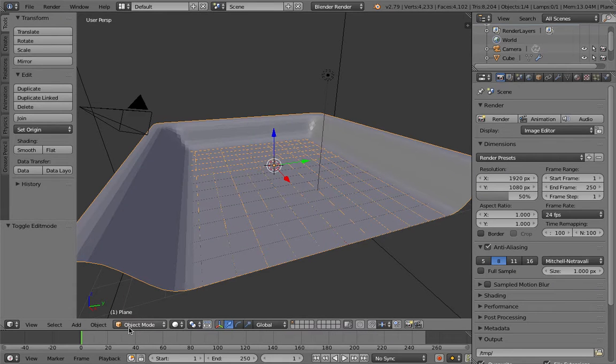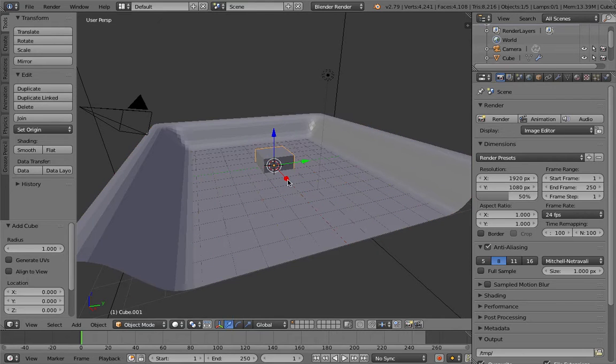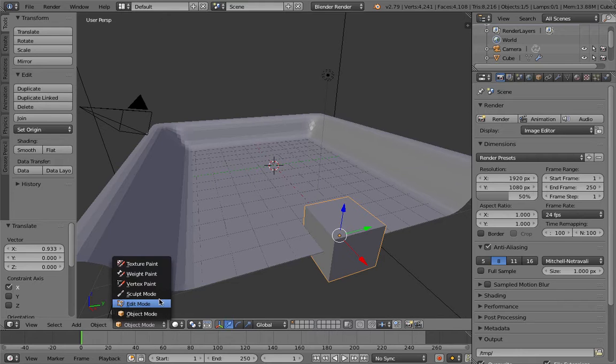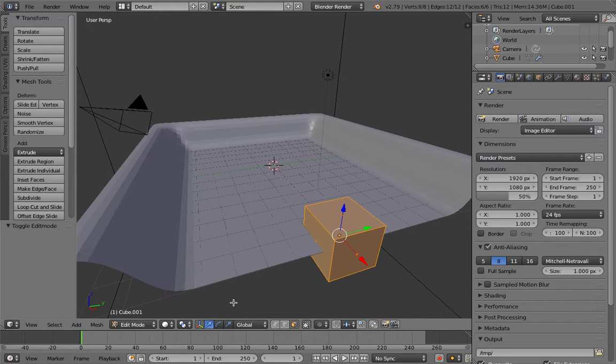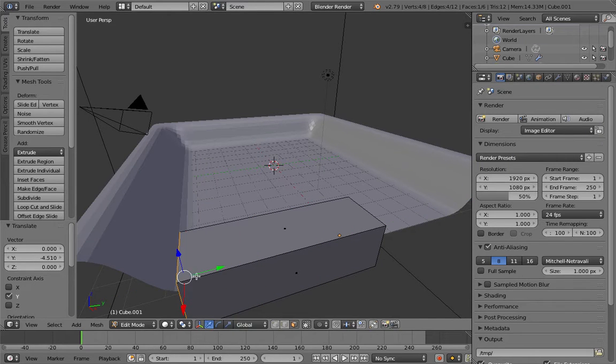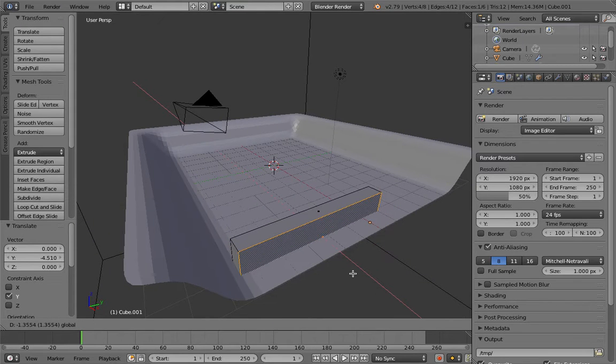You go in object mode and press Shift plus A, add a cube, and just kind of press F, and then scale it out and then go back onto edit mode on this cube, and kind of give it down like that, if you know what I mean, and scroll it in a little bit so it's like this.